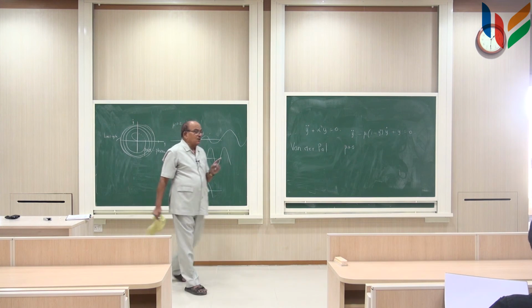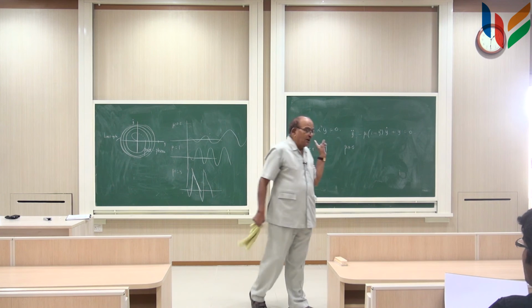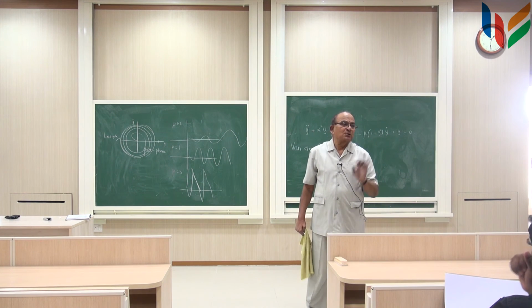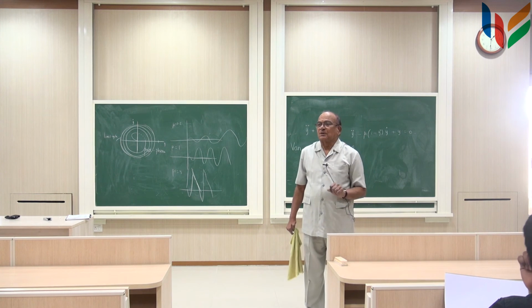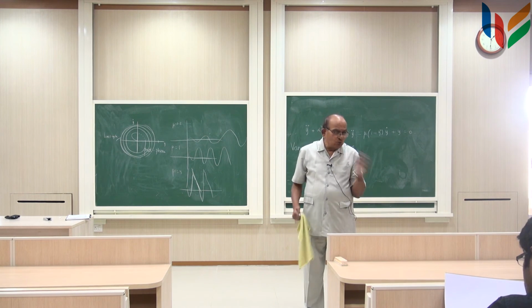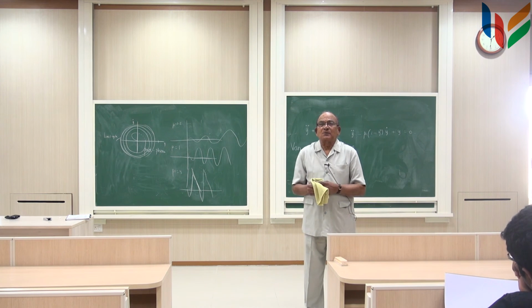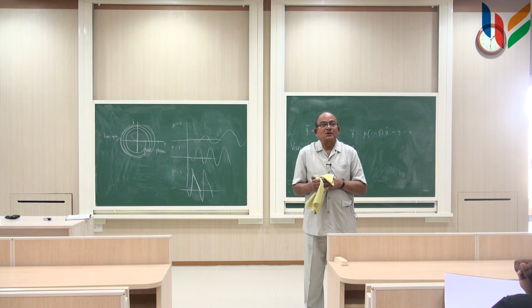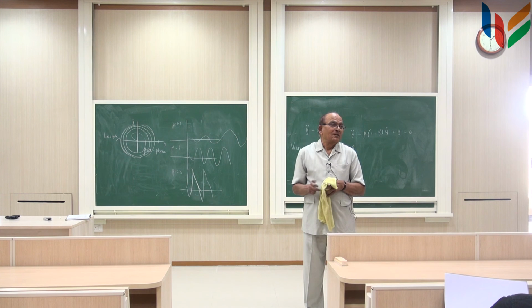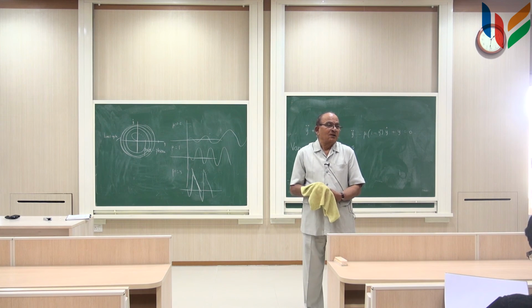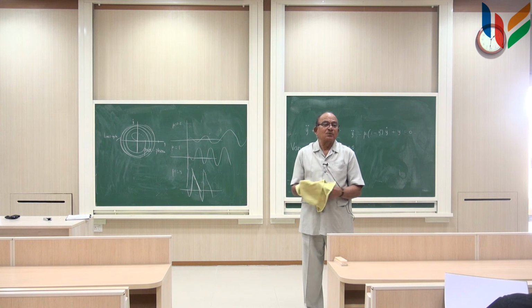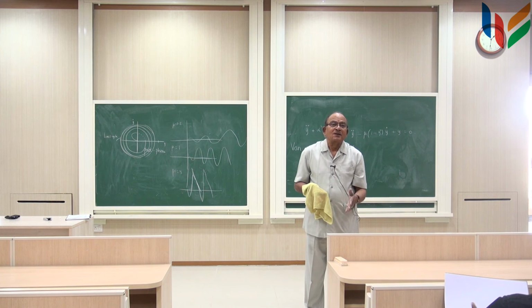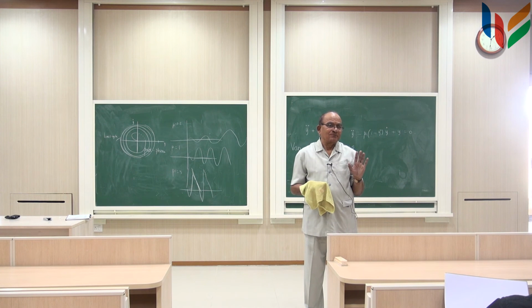So, to study oscillators, we really have to find out some analysis like this to see what is the stable amplitude and what is the stable frequency of such systems. But what we do simply in analysis of amplifier oscillators in courses like this is assume that the linear model holds, because that is the easiest thing that we can do. So, we assume that the linear model holds good and then analyze for the linear model and then say that as long as there is a pole in the right half plane or on the j omega axis, it will have a sine wave oscillation.